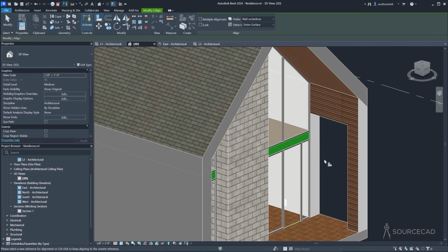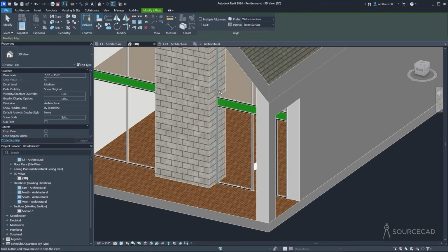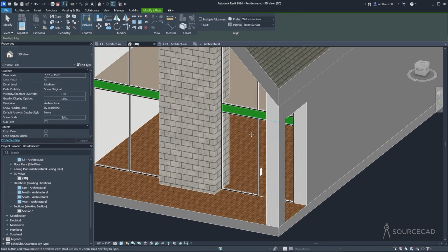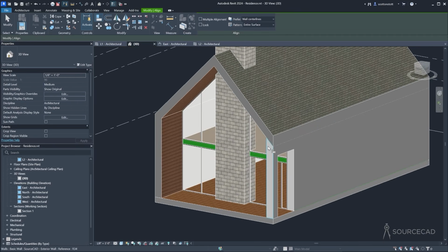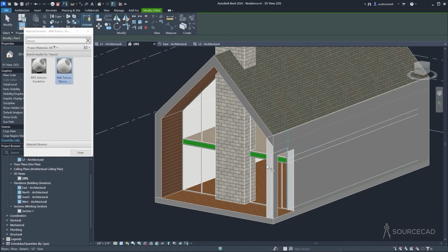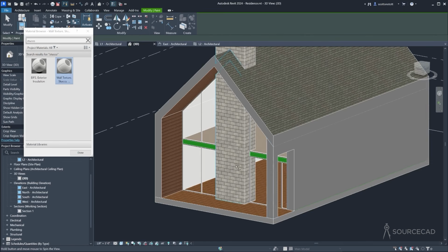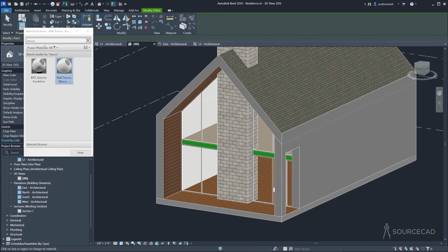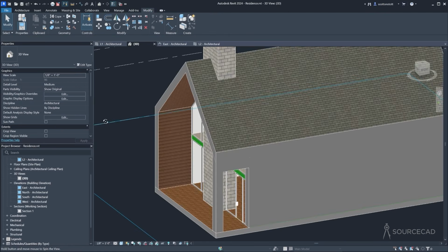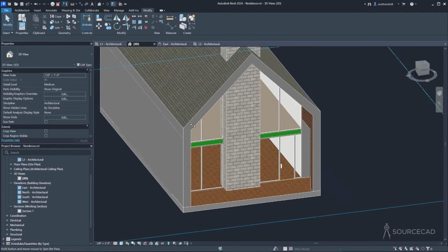So we see the stucco material wrap around, and it's kind of the way I wanted it. This is more like a column now. However, I'm noticing that we have the wrong material on this surface here, and probably on that surface. So we want stucco there, I believe. I'll go to Paint, Stucco, select it, and paint these surfaces correctly. Yes. This line isn't right. We don't want to see that. Line work, invisible lines, click on that to eliminate it. Great. So it's coming along nicely.